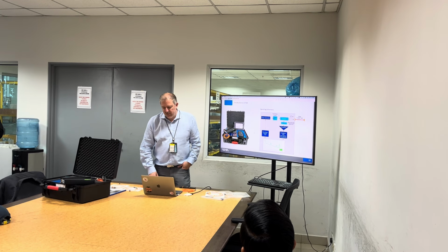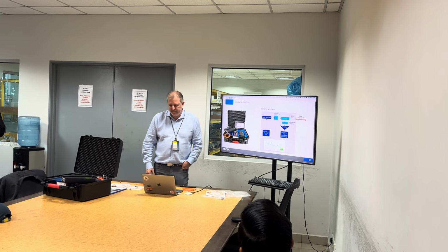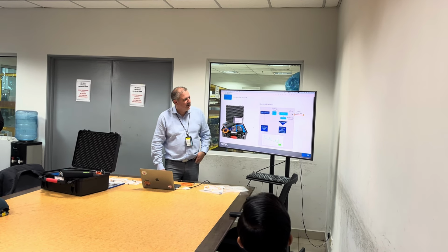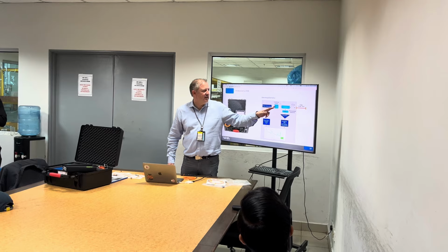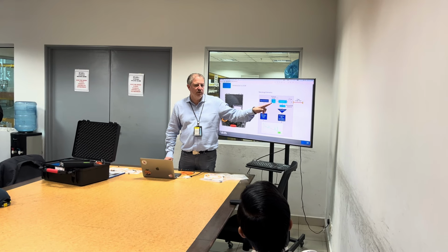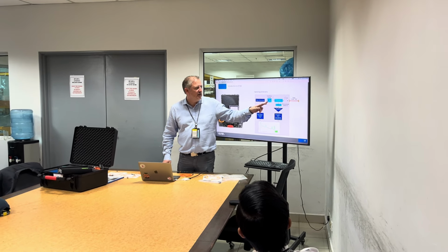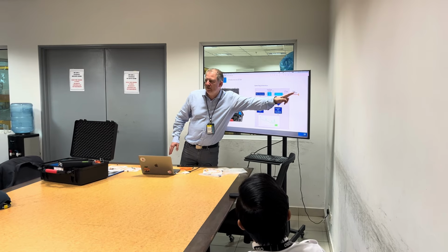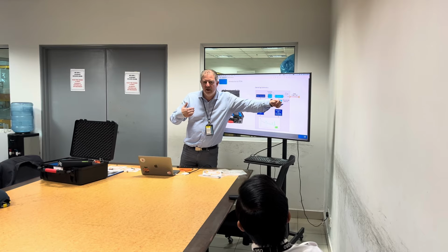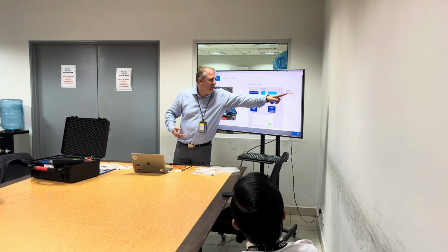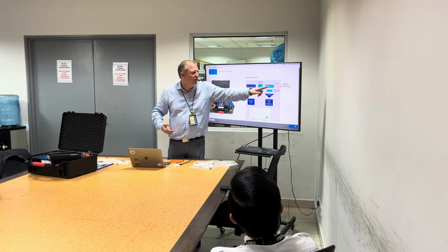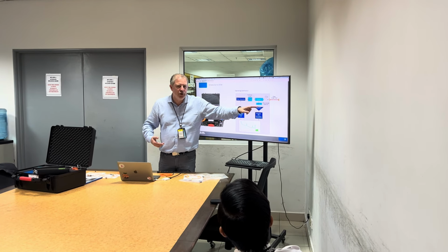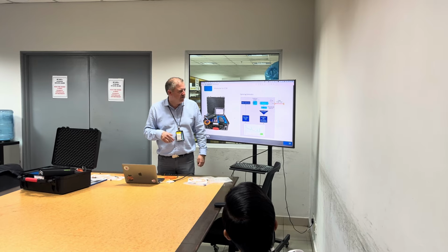This is how it works. Basically, there's a pulse which is sent, usually from a laser diode, that goes through the fiber under test, and we look at everything that bounces back, every reflected light that would go back, and then it goes through the coupler, and then we have a photodiode detector where we can measure the amount of light that we have.